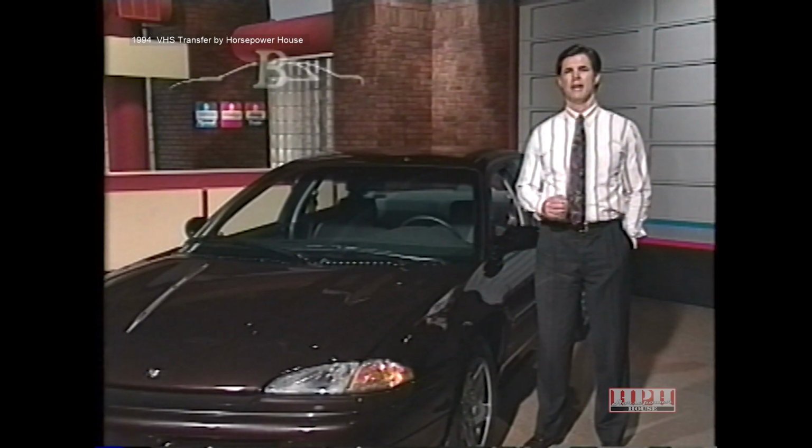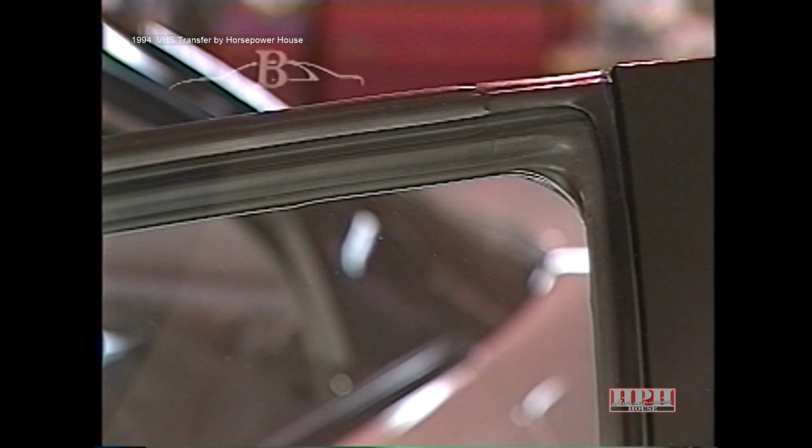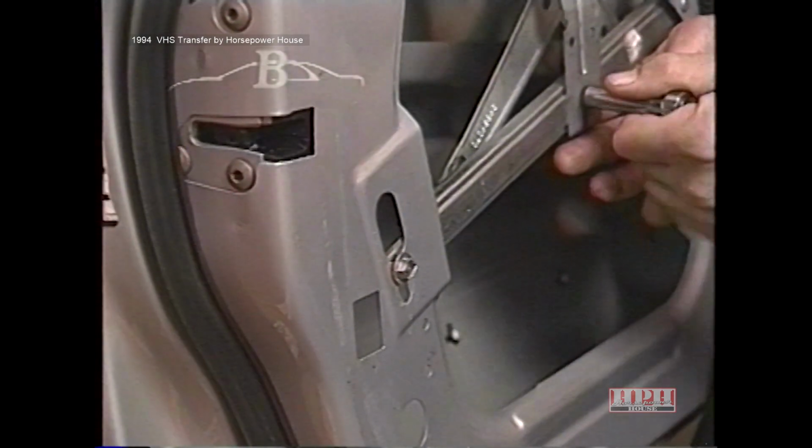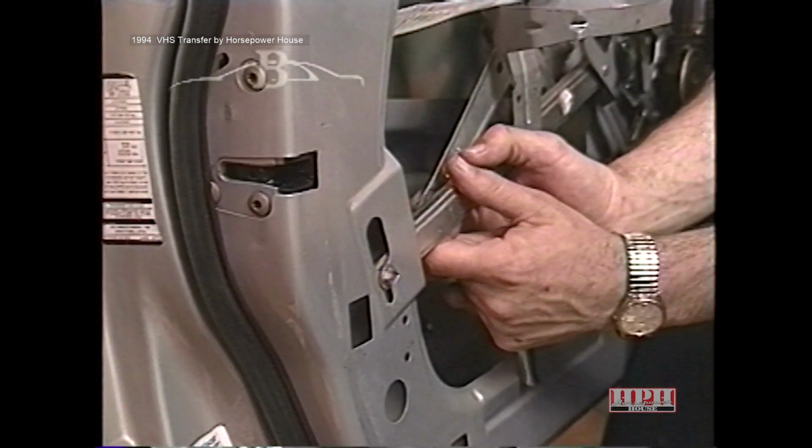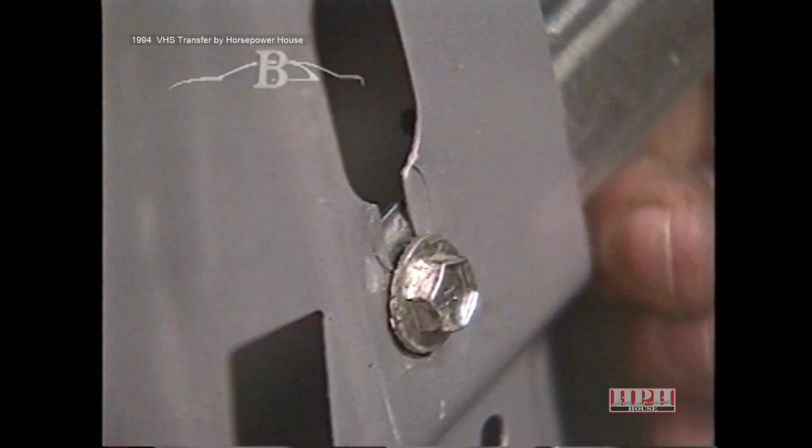Keep in mind, however, that doing this may require additional hinge and striker adjustments to ensure a good fit and good closing efforts. However, if the top edge of the door is flush with the roof, check to see if the door window is well inside of the weather strip in the raised position. If the window is pushing hard against the outer edge of the weather strip, refer to your service manual and adjust the trailing arm of the window regulator so that the window is properly positioned inside the weather strip when in the raised position.